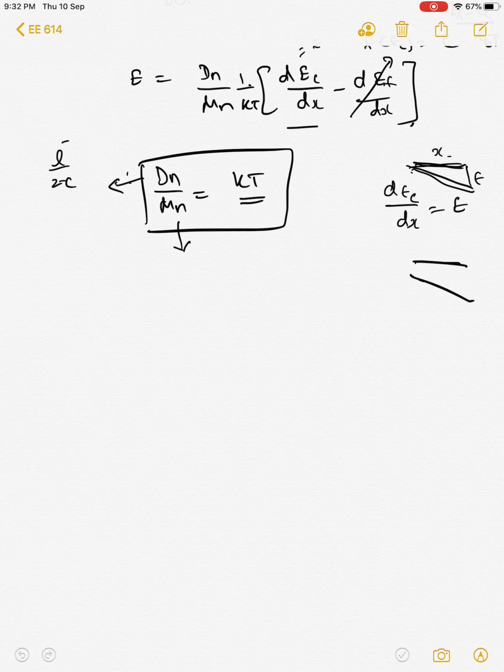The last time, in the last lecture, we had a discussion on diffusion and some constants like the diffusion constant Dn, and the ratio between the diffusion constant Dn and the constant in the case of drift, that is mu n. And then we found that the ratio is a curious relation with dependence only on the temperature. It was an interesting fact, and then we stopped at that point.